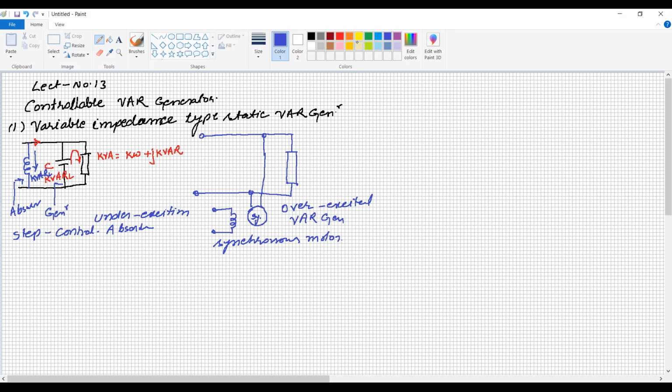So, for example, if I draw the vector diagram for that synchronous motor, say this is the active energy. Say a kilowatt plus j kVAr is needed from the source, so it is the active power of the load. Say this is the initial power factor angle of the load, theta 1. Now this is the synchronous motor, but the synchronous motor also consumes some active power, and it may work on the leading power factor or lagging power factor.